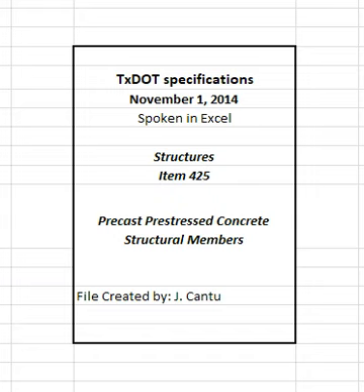Assign an individual lot number to all bars from each size and heat, all wire from each coil, and all strand from each reel, and tag the material for accurate identification at the job site. Identify each lot of anchorage assemblies and couplers in a similar manner. Unidentified prestressing steel, anchorage assemblies, or couplers received at the site will be rejected. Loss of positive identification of these items at any time will be cause for rejection. 2.4 Post-tensioning system. Furnish post-tensioning system as required by Item 426, Post-Tensioning, and as shown on the plans.